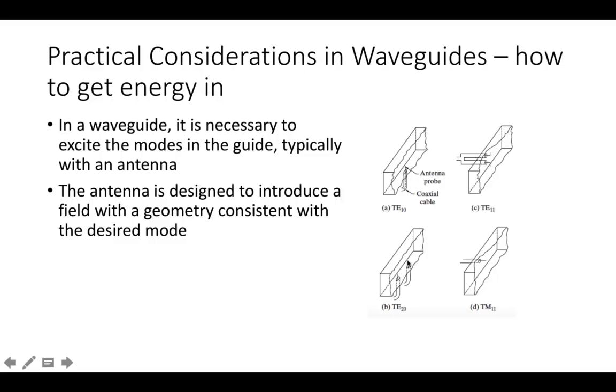Now that doesn't mean that if you try to excite a TE20 mode, you won't eventually get some mode mixing and mode degeneracy. You'll have some TE10 that'll eventually mix in, just because that is just the nature of the beast with waveguides.